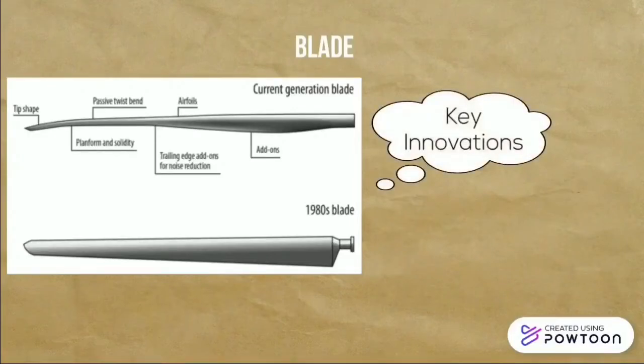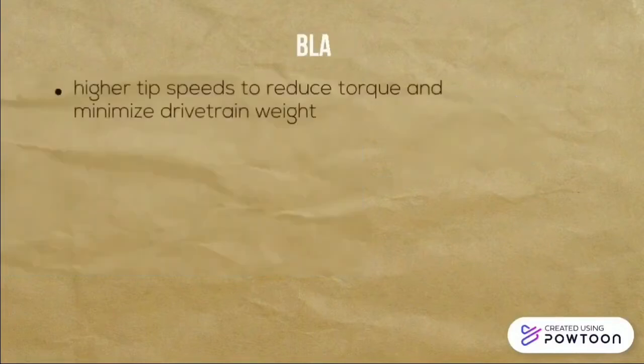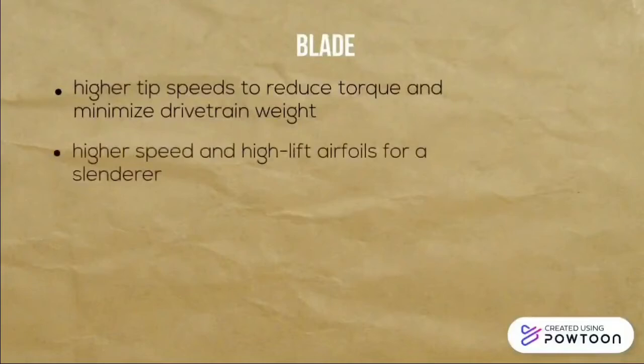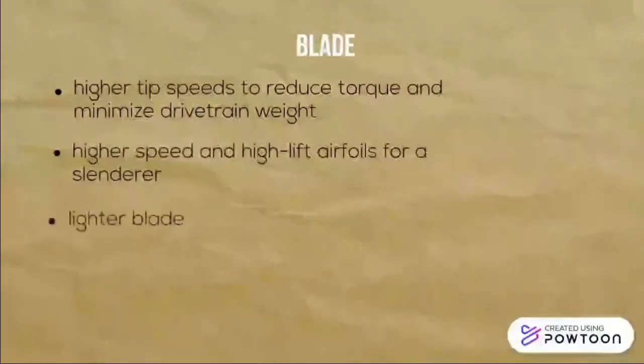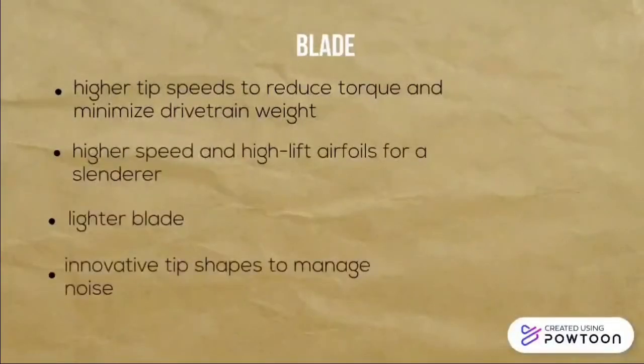So what is the key innovation that had been done? Higher tip speeds to reduce torque and minimize drivetrain weight, higher speed and high-lift airfoils for a slenderer, lighter blade, and innovative tip shapes to manage noise.